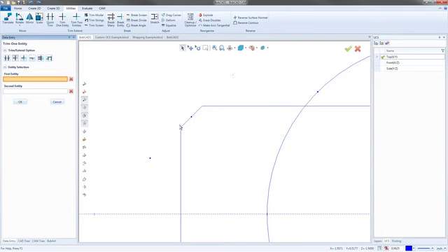I use that a lot on tricky geometry when I'm doing just engraving and stuff. And I just want to be able to extend. I want to draw my own leads. I just extend the line however much I'd normally add in for the lead in. And it's a real easy way to do that. You can modify an entity, just so you guys know.